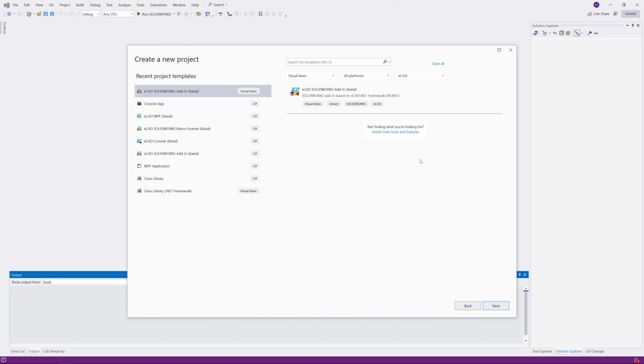And instead of creating this using standard elements such as extrude and a sketch, we want it to be a new feature which the user can edit. It should have its own custom property manager page where the user can enter parameters such as height of the cylinder, diameter of the cylinder, and the location.